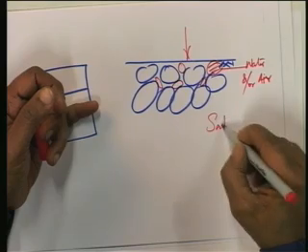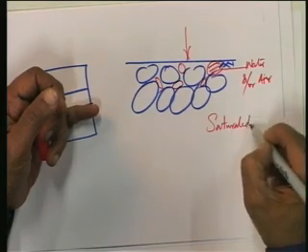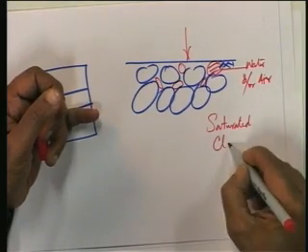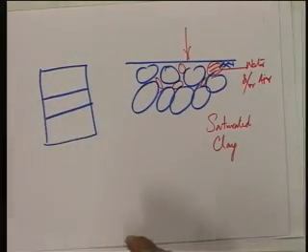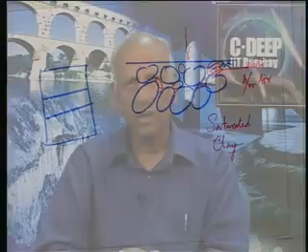And if we do this kind of thing, when we apply a load on the soil and suppose the soil is saturated, meaning there is no air, and suppose we are considering clay, then there are a number of things which will simultaneously take place. One is there could be a compression of the solids, there could be a compression of the water phase, and also probably air if some air is there, if the soil is not fully saturated. If it is fully saturated, air will not be there, and therefore, there is no question of compression of air.